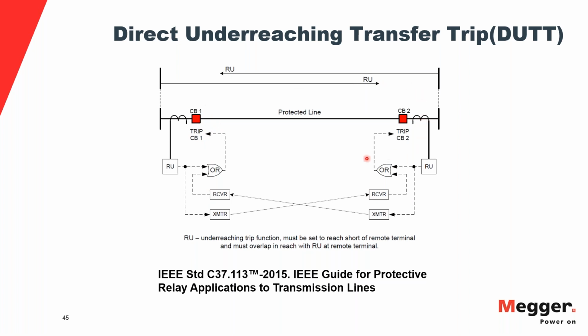Now, zone 2 is usually tripped around 20 cycles or so. So even though this guy tripped immediately, this guy is going to wait 20 cycles to trip. Now, in the case of the scheme, we have this guy tripping immediately and then sending a trip command to this guy here, which is going to trip the breaker immediately. We're going to trip a lot faster with the scheme than we did without it.